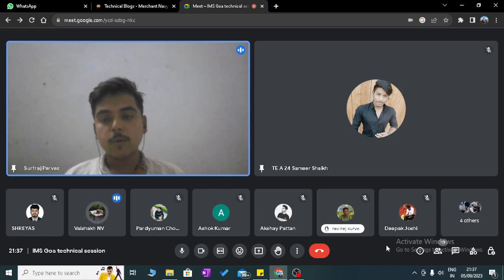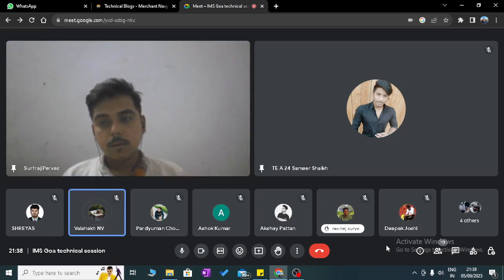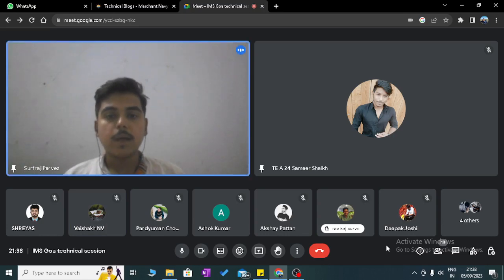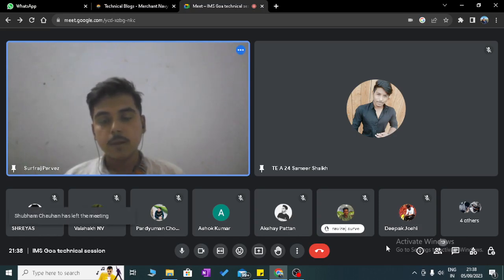Yes, one more point. Centrifugal pump can pump only water, or can it pump oil? Centrifugal pump can't handle gas, right? Correct. And centrifugal pump also can't handle high viscous fluid. A positive displacement pump can handle fluid with a higher viscosity. This is also a difference. We can add it in our explanations.